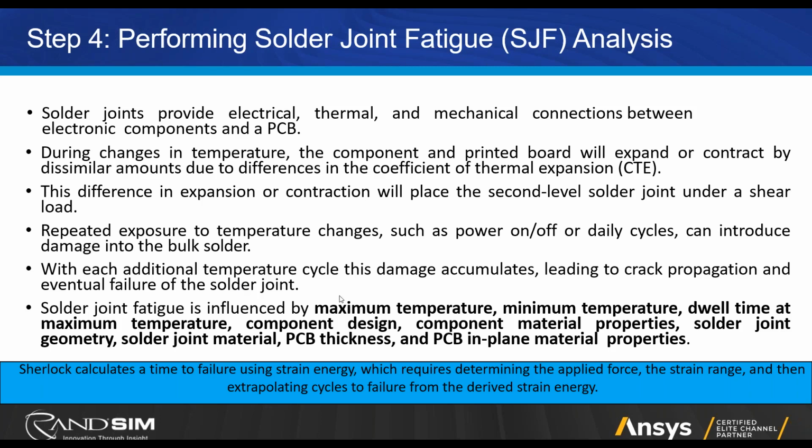It's influenced by the maximum temperature of the temperature cycle, the minimum temperature, how long it's staying at each temperature, the average temperature, and your components and the electrical properties of your PCB. Behind the scenes, Sherlock is actually calculating the strain. It is doing a mechanical simulation using that thermal information. That is the method by which it's figuring that out.